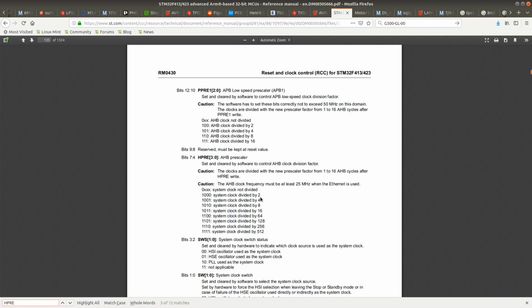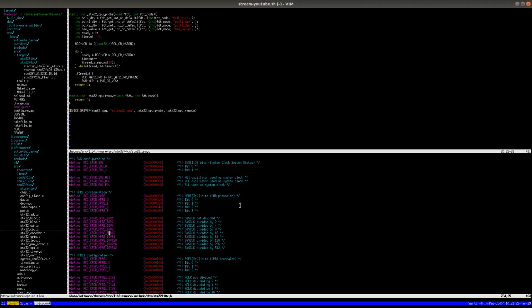So if I specify 4 in the device tree, then I need to basically find just the first set bit in this value and reset all of the other bits. And there is a function for this. I've done this before somewhere. There is actually an instruction for this, so you don't have to loop through it to find the bit.